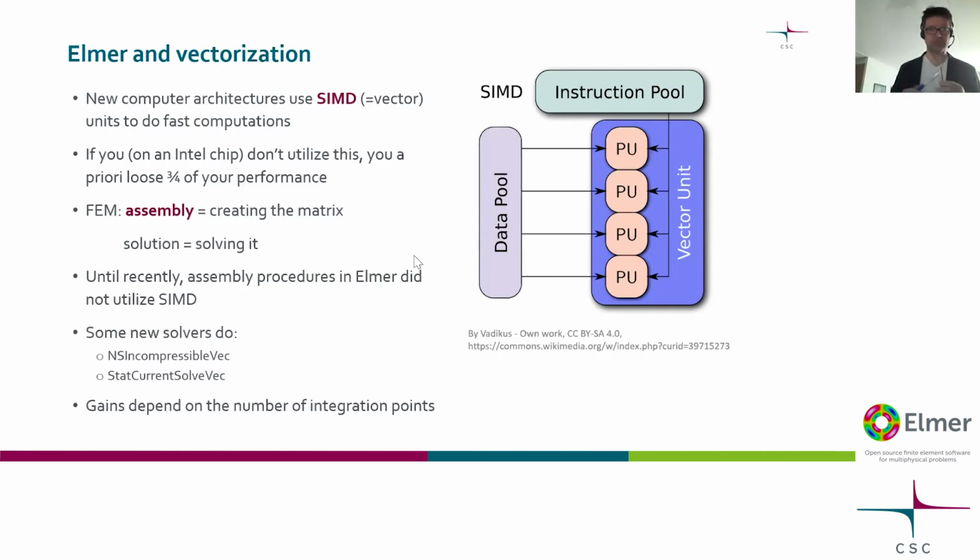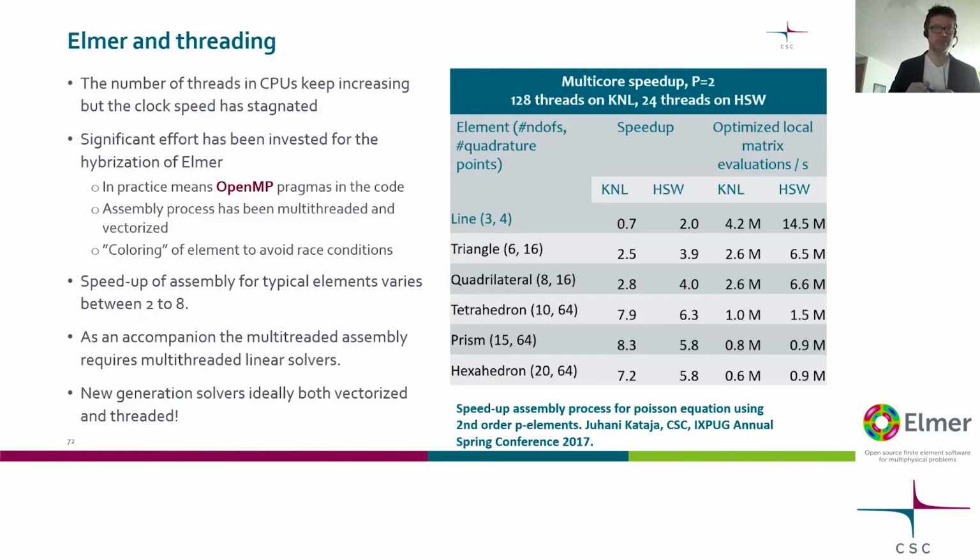Naturally, vectorization needs a certain concept. SIMD is single instruction, multiple data. So you have to provide a large array of data that can be processed with the same instruction. Having more Gauss points in your element helps to do that. We have, for instance, simulations now in glaciology where we have 44 Gauss points for one element. And then you can just treat the whole element in the vector unit, and this will be very effective. Okay, can we have a look at the next slide, please, Peter?